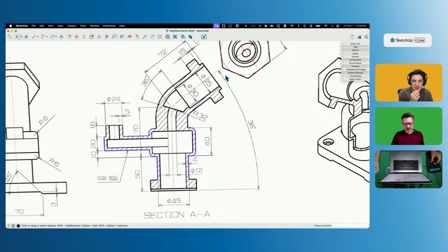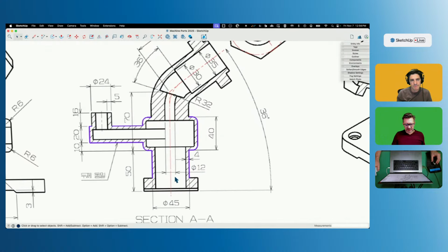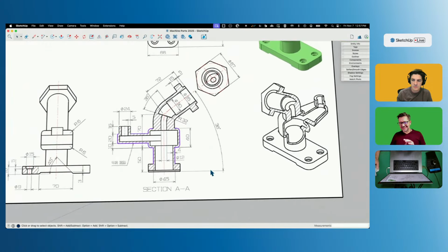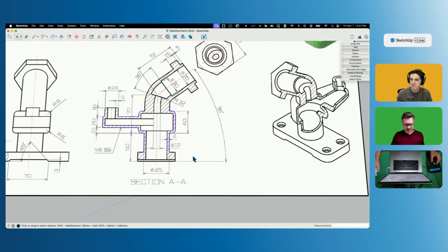And then what I can do is just start working my way down and chopping them and connecting them one at a time. I think that's how I'll do it. Actually, I don't have to do that with all of them, only with these three. This one will just be a push-pull, widen it, push-pull, widen it, come up to here where this angle starts, and then the rest will be follow me's. So that's my thought. I almost want to tackle the interior before the exterior just because I'm not 100% sure what I'm even doing there. So let's do that.